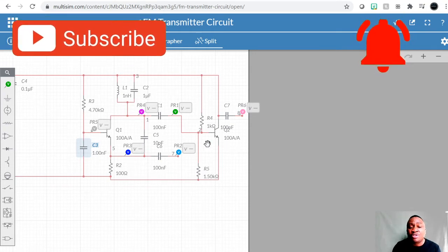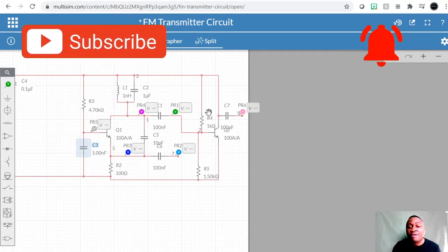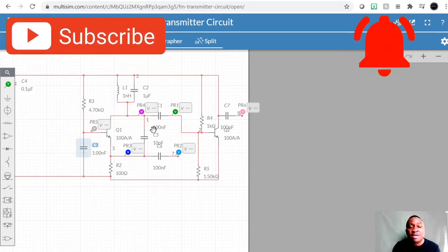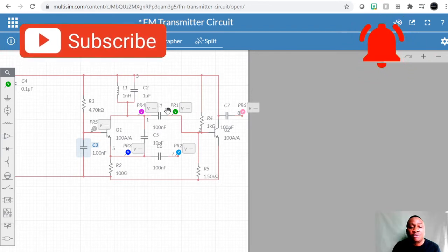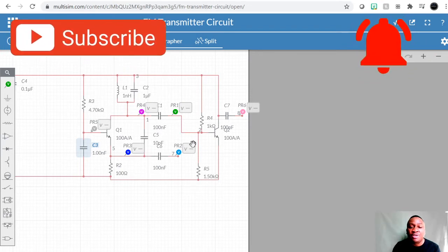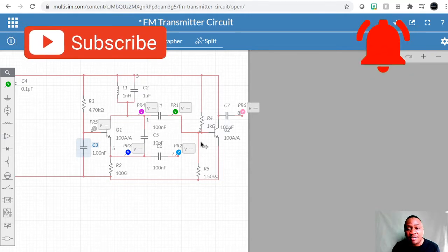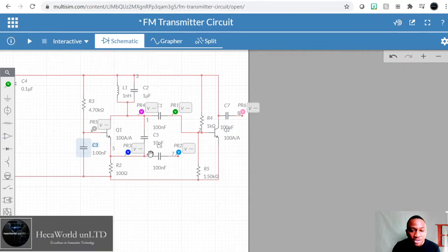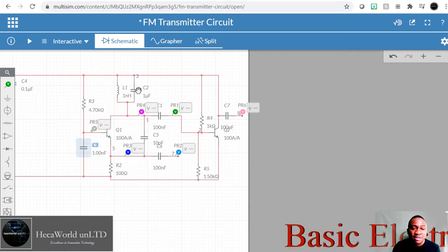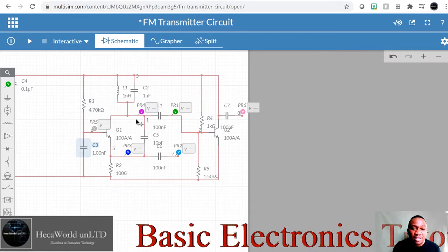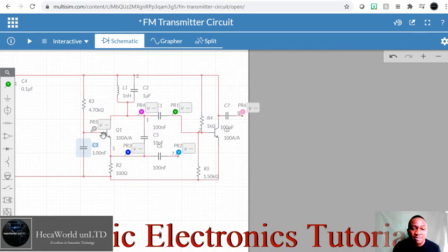The rest of the components are the RF amplifiers to boost the RF signal coming from this circuit. In this case, we're taking the input of the RF amplifier from the collector circuit, and I think that's where our antenna comes from. That's it basically. Bias your transistor as an amplifier, have a frequency determining network connected to that amplifier, take a portion of it and feed it back into the input circuit.